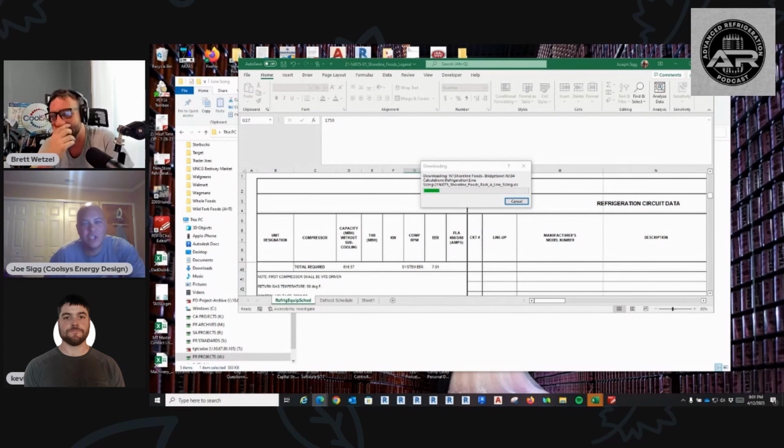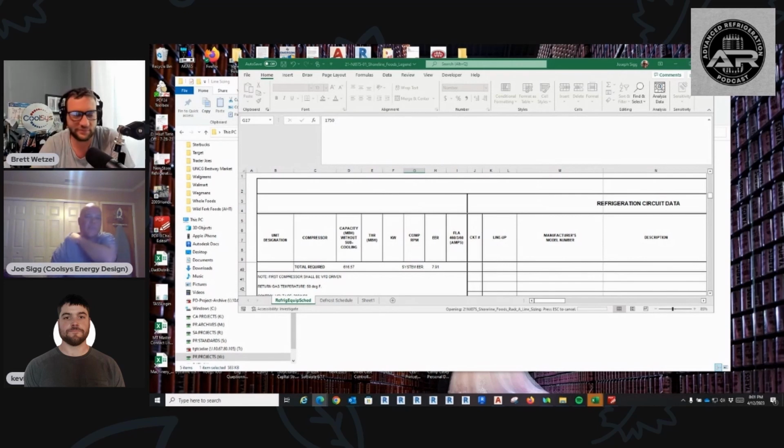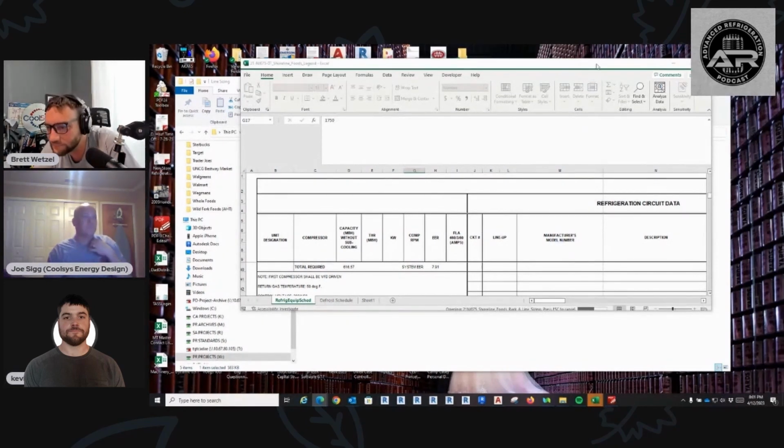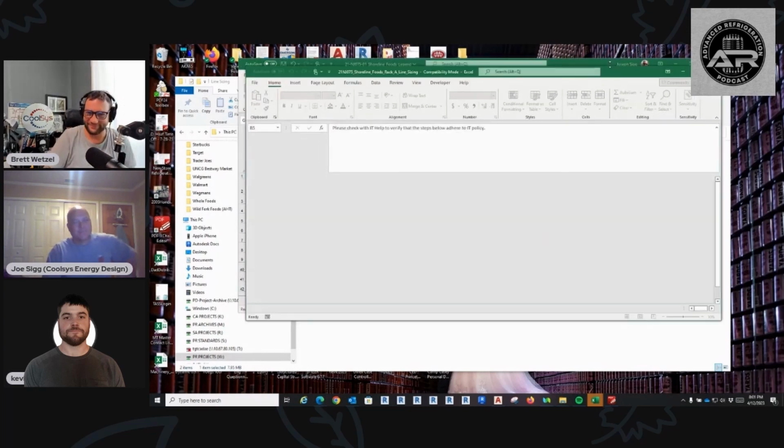It's just like hot gas bypass in an HVAC system, right? It's the same idea. You're just keeping some load on the system to keep it running. Gotta get that zero zone hot gas bypass valve. Thing's just like throwing a hot dog down a hallway. That thing is just wide open. You want to try to maintain those compressors, keep that load up. It'll add that superheat right back to them, so you don't have to worry about liquid flood back on that.